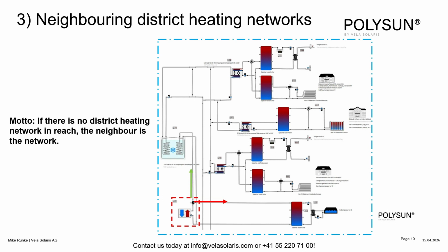So a key planning consideration: due to the constant waste heat stream from the data center, the ice storage system can be designed more compactly and cost efficiently. For peak load situations, short-term buffer storage or medium-term load-based operating management and seasonal large-scale cold storage are all used.